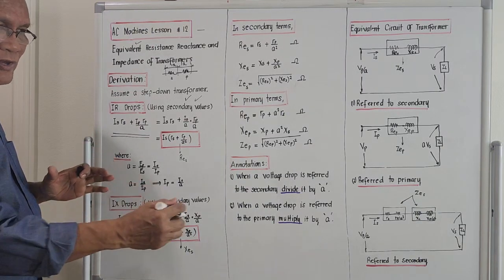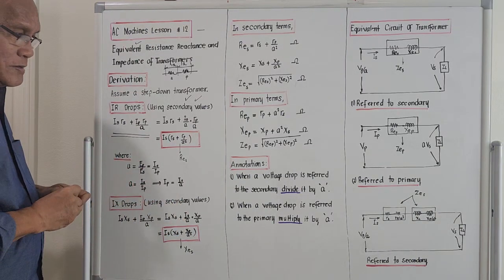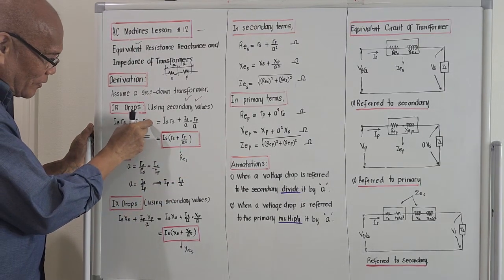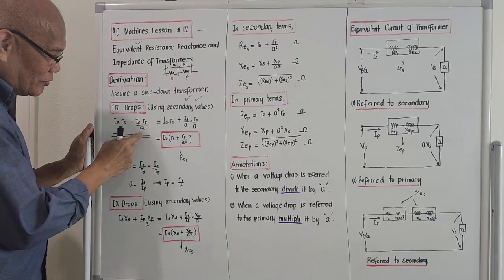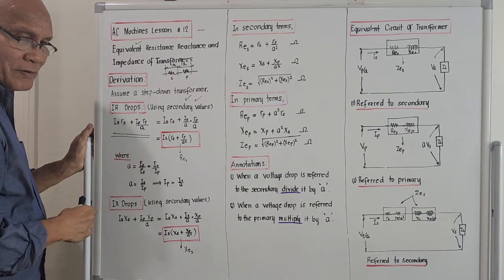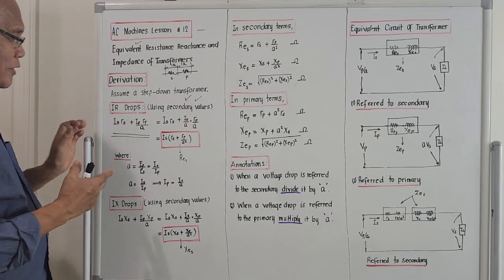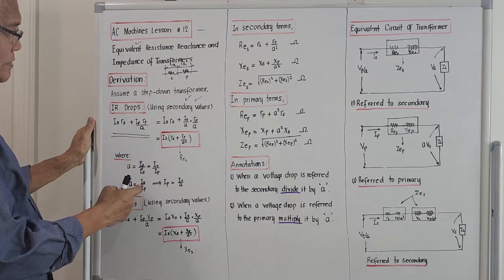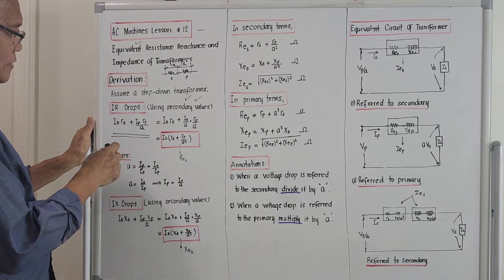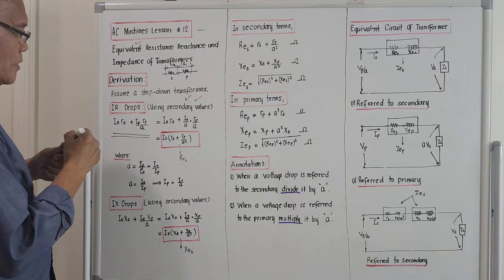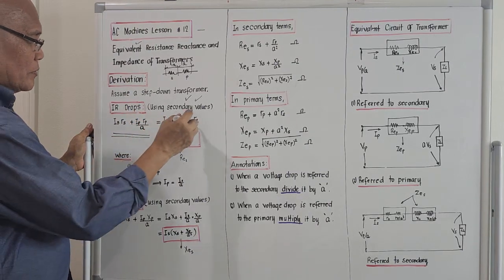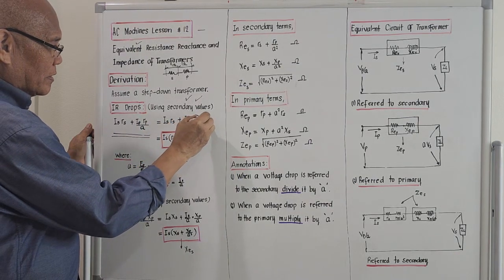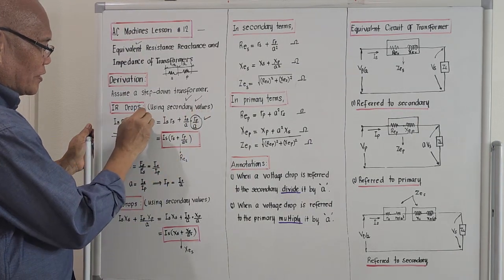So they will be of the same classification. This is secondary. This is the voltage drop on the primary, but for it to be added on the secondary, we will divide it by A. Okay? So if we now try to simplify this one, this will be ISRS. Then we try to replace, we get this RP over A over here, right? And what remains is IP.